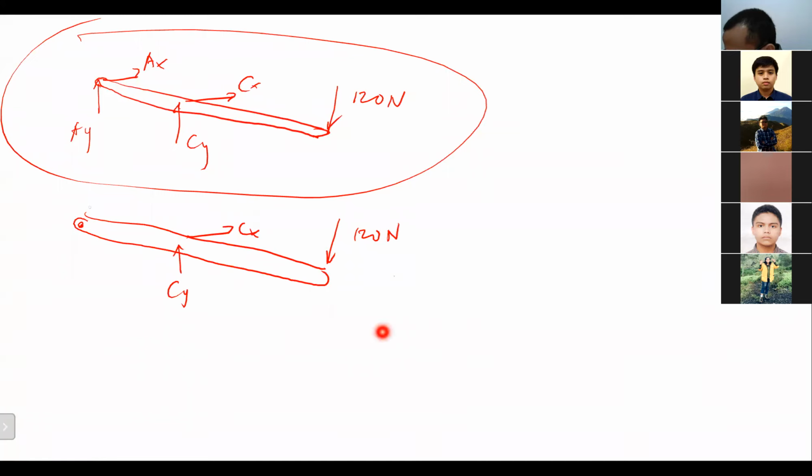If you just want to represent it with one force only, this FA here, we don't know the magnitude, and here, the direction theta A, we don't know the theta as well. Do you get it, Asya? Yes. So basically, if we do a vector summation of AX and AY, what we get will be FA like this, right?